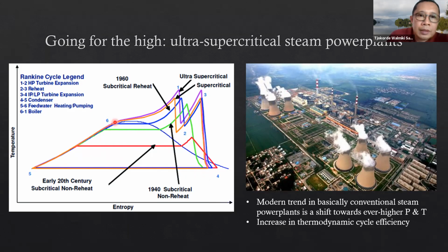Okay. So from point 1 here, start from here, expansion, and then that's expansion, reheat, expansion again, and then this one is pumping, I think. There's one here, and then that's heat absorption, right? That's heat absorption, and this is the reheat, during the reheat cycle. So what am I saying here? From 6 to 1, that's not reheat. This is the boiler. Going from point 6 to point 1 here, this is the boiler.